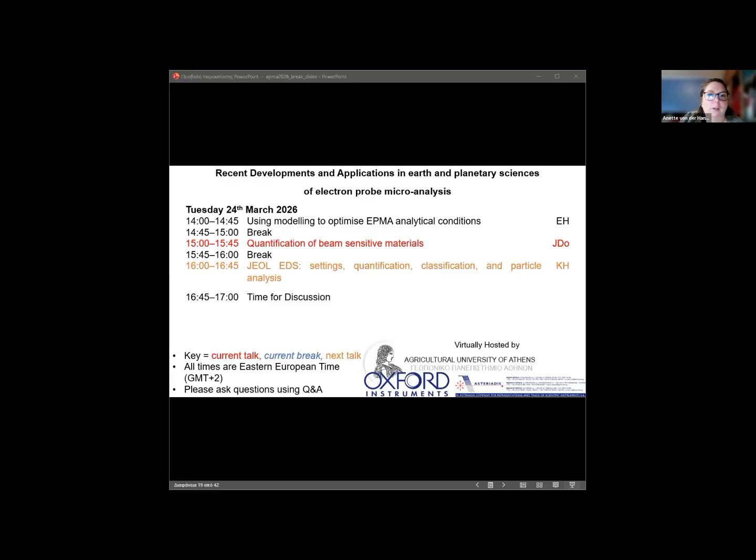The absorbed current tracks if you have compositional changes or charging or something, and that gives you a good first order indication if maybe you need to widen the beam diameter or lower the current, even without TDI tracking. Yep. Maybe there are conditions where you can be okay. Yeah. First figure out if there's a problem and then deal with it.